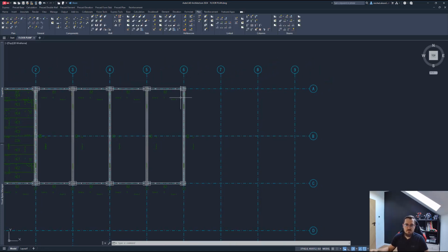And with that, let us go ahead and start actually working with sandwich panels. We'll create a small building on the side of that big storage facility or factory of sorts. So under the walls tab, basically what we'll do is click on the create or draw wall icon, and we'll select what type of wall we want to create. For me, I want to create sandwich panels. And like that, I can immediately start placing sandwich panels.